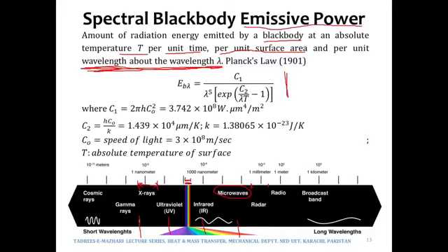So if we add up the radiation emitted in the X-ray band, the ultraviolet band, the infrared band and the microwave band, what do we get? We get the total emissive power. Means that if we integrate this E_b lambda, see over there in the intensity, what did we have? We had E_b phi, because radiation intensity is related to direction, whereas spectral is related to a particular wavelength.